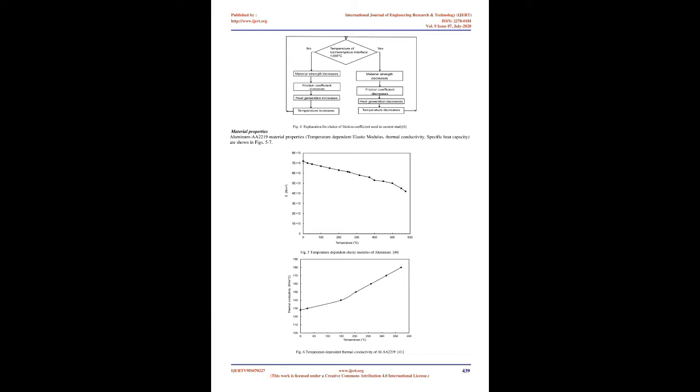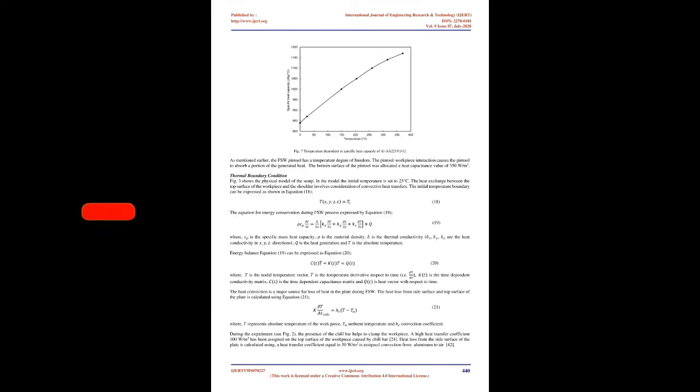The plate is modeled using an 8-noded 3D temperature-displacement coupled element, C3D8RT. This type of element has 8-node trilinear displacement and temperature degrees of freedom, and reduced integration with hourglass control. In this model, a single plate is modeled rather than two plates to avoid contact complexities. The entire plate was assigned as an adaptive domain, which allows the mesh and the material to move independently of each other. The top surface of the workpiece is considered as a sliding surface, where the mesh follows the material movement in the normal direction to the surface and moves independently of the underlying material in the tangential direction.